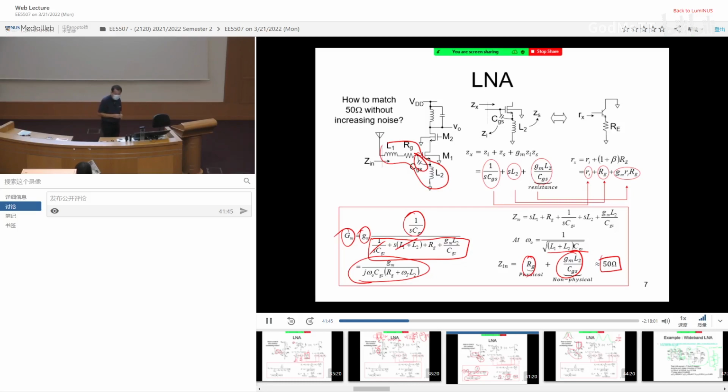So for this kind of amplifier, nowadays, narrow band design is fine, but if you look at the RF standards nowadays, I have Wi-Fi at 2.4 gig, I also have Wi-Fi at 5 gig, right? Now, if I design a narrow band LNA, it means I will need 2 amplifiers. Agree? But that is not good.